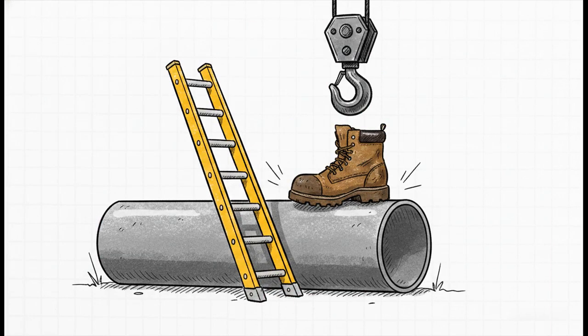The answer to that is just practical EPC reality. Experienced engineers know that pipes have to survive the physical, chaotic environment of a construction site. A pipe with a paper-thin wall would dent or sag the literal second an operator leaned a ladder against it, or a rigger dropped a wrench on it. So Schedule 40 is frequently used as a practical, robust structural baseline. In these cases, the schedule isn't protecting against internal fluid pressure at all. It is entirely there to protect against human error and gravity.